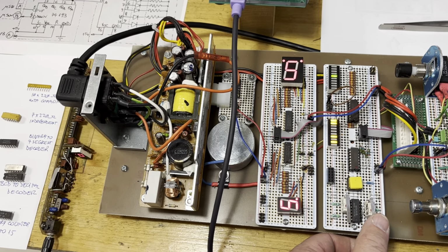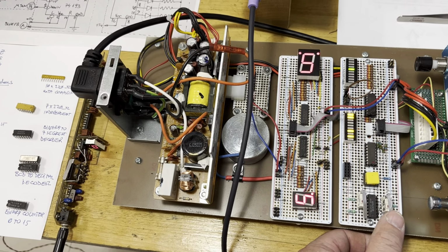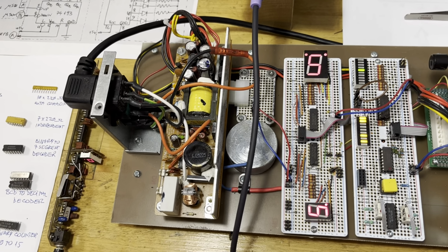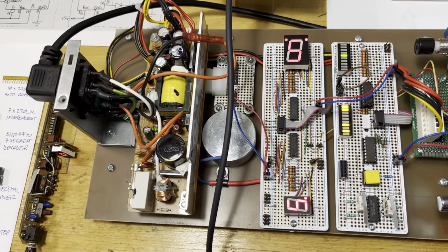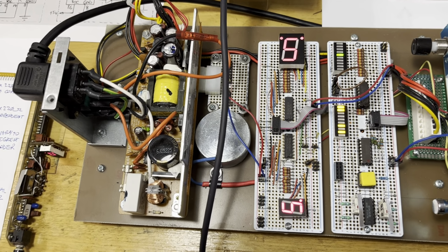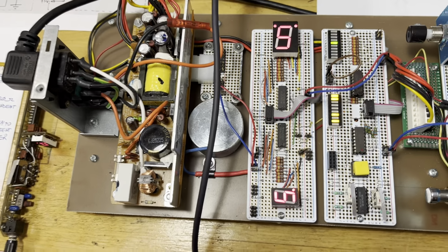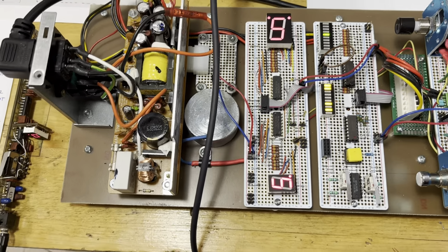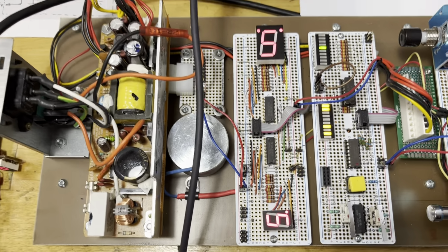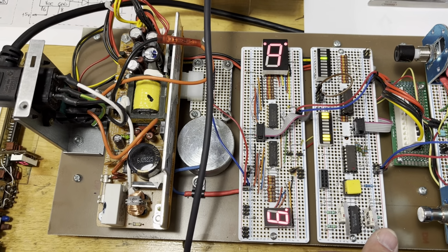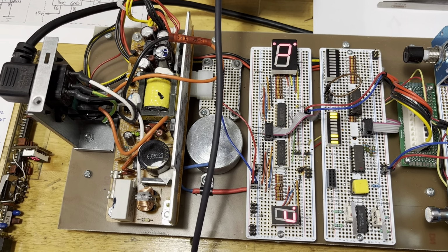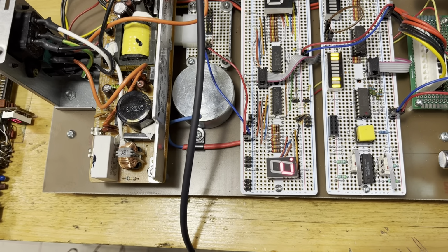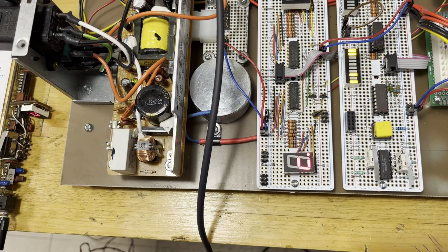Now we're going to use a counter, which is a binary one with 4 outputs, and because it's counting 0 to 15, we're going to call it a hexadecimal counter, simply because it's able to count up to 16 combinations from 0 to 15, okay? Now if you want to display numbers 0 to 15 on one only figure, like here, something strange is going to happen. Instead of showing you the number 10, because it's not possible to have the number 10 displayed on one digit, you are going to see that very strange symbol here.